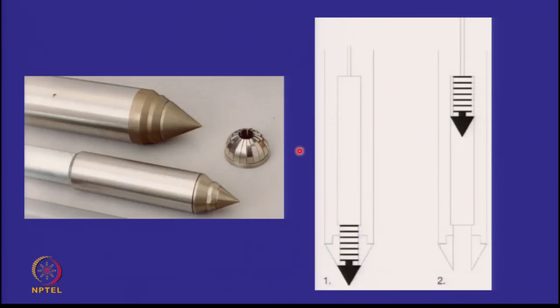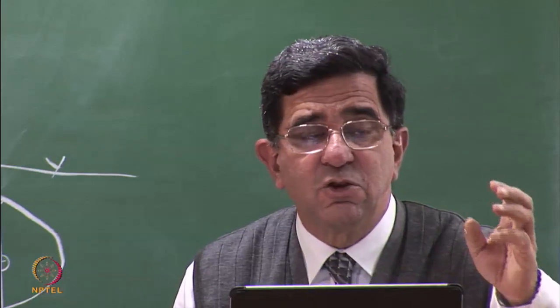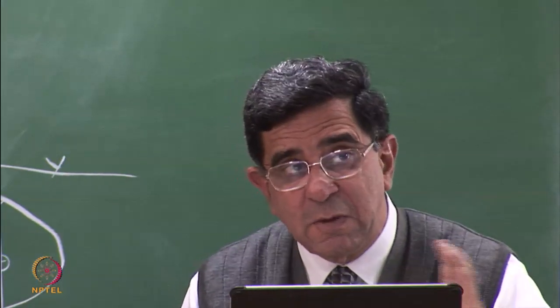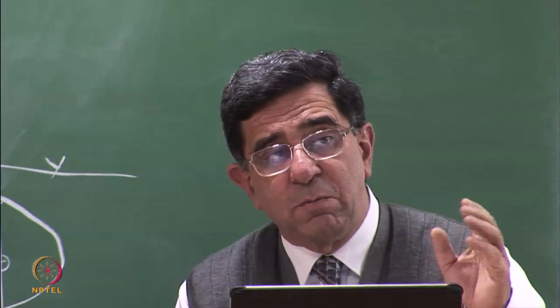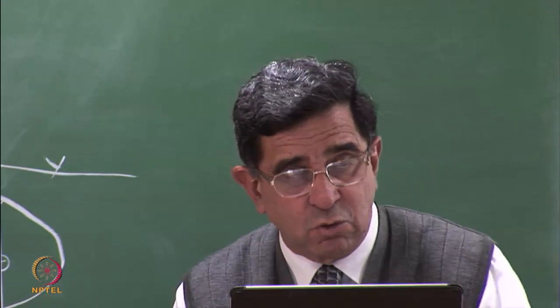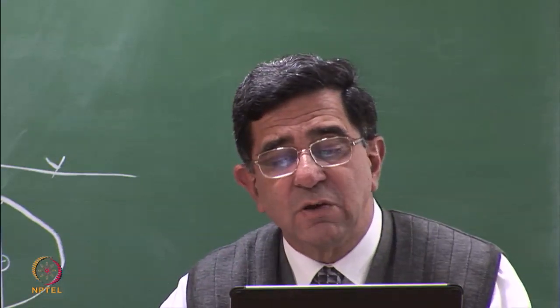And how is the sampling done? This is your traditional electrical cone. This is a cone with a sampler. This outer sleeve becomes a piston sampler. When you go in, the cone is here, the sampler is around. When you have reached the depth of sampling, you can retract your piston and push this sampler into the soil and get the sample in this space. So the cone penetrometer, which is normally without a sampler, has to be now used with a sampler and becomes a more expensive equipment. So first do the cone penetration tests to identify the high permeability zones, then go to the high permeability zones and pick up the samples.